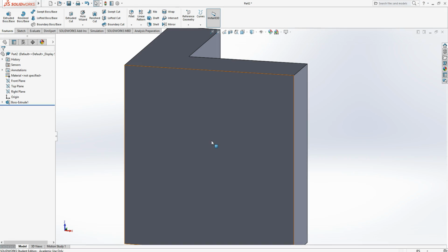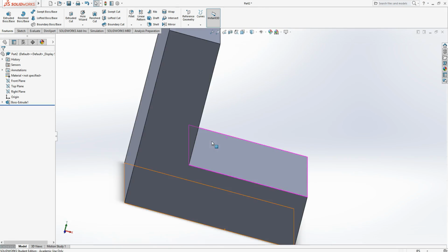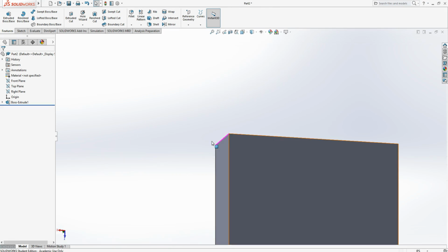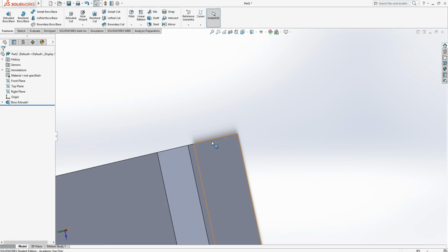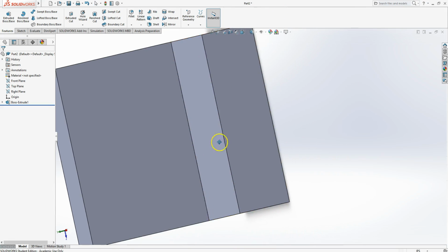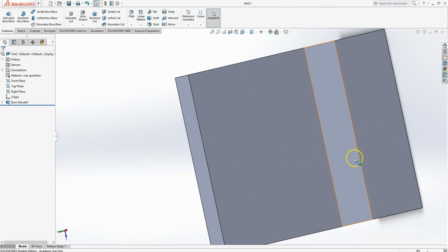Now, you can use shift commands to rotate your item. Hit shift up, you can rotate to that axis. Shift left and right, rotate to that axis. You can hit control center mouse button, you can pan left and right. Use what's comfortable.